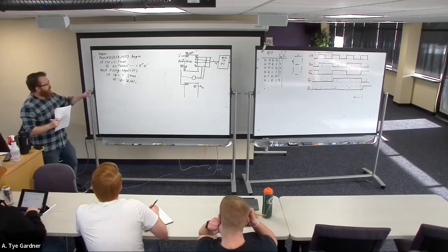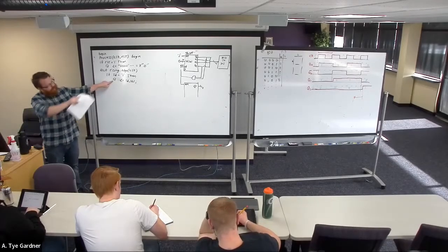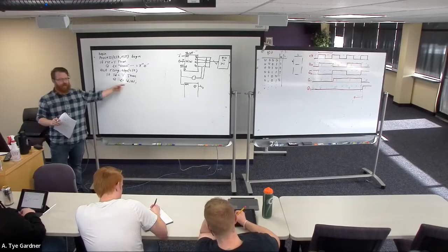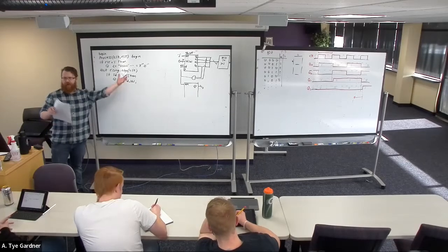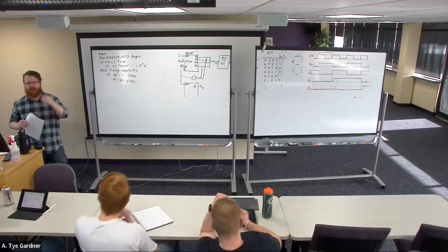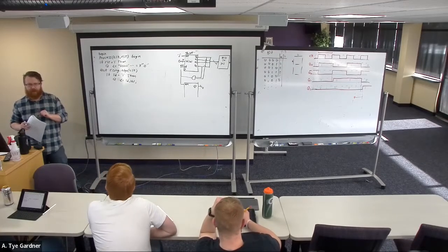And this question keeps coming up. So Q is 4 bits, right? In that picture, load val is 4 bits. I don't need to do an index on this because it's going to take 4 bits and stick them into 4 bits. Everything works. The only time I write the index is if I'm using some subset of the bits in an array.